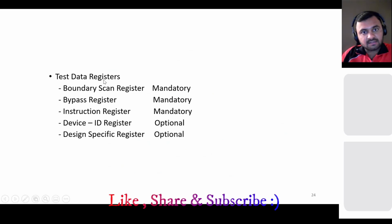So in the test data registers, we have some mandatory and some optional registers. There are many more, but these are the basic ones. So these are the boundary scan registers, which I told you about, like around the pad we have a boundary. So those are mandatory. Then we have a bypass register.